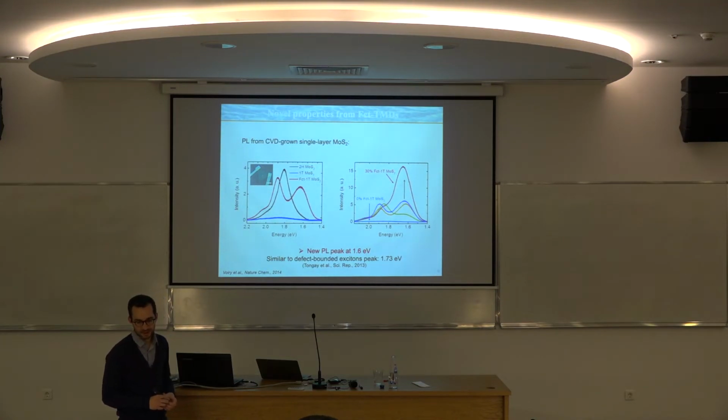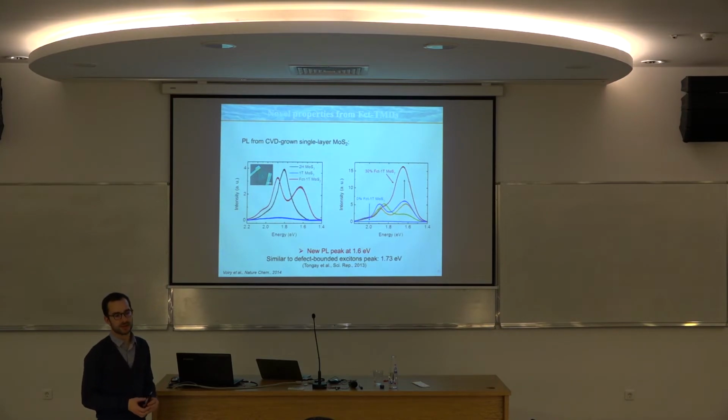That's actually a good question. I didn't mention it because, from my experience, it's very easy to oxidize. I tried a couple of times, just with chemical exfoliation. I didn't try any reaction with CVD-grown flakes. But on chemically exfoliated materials, I have like 50% tungsten oxide after the reactions. So it was too oxidized to work with. In the results I'm showing today, we cannot detect any oxides. But tungsten diselenide, for some reason, is very sensitive toward oxidation.